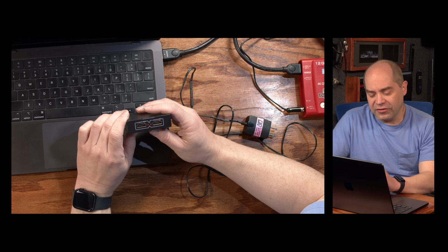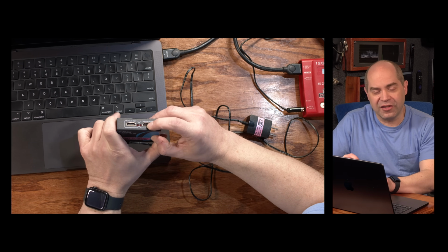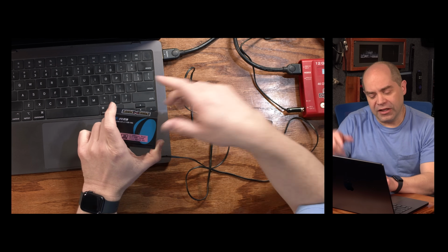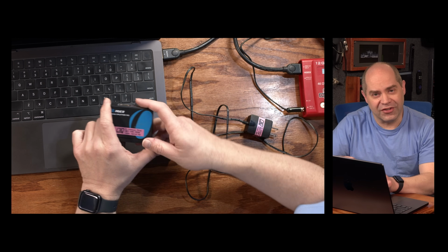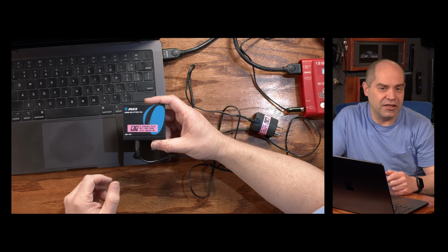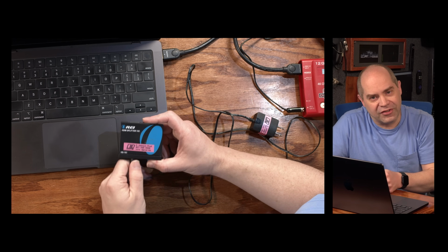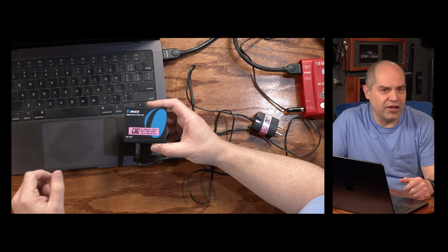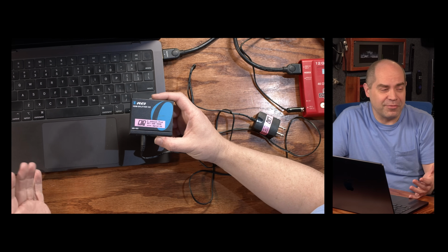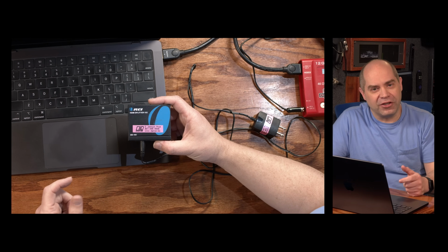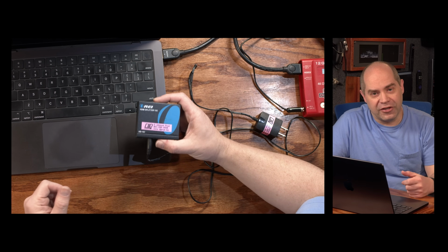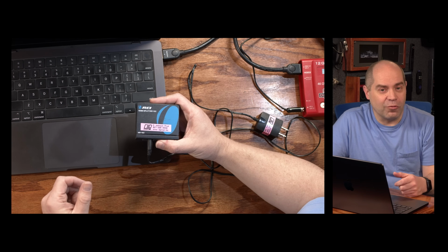So what happens is we take HDMI output 1 and we run that into a monitor or television or whatever, and then we take output 2 and run that into our video production system. And effectively what happens there is the computer is negotiating with the television for that EDID information rather than our video production system. And I find that that actually generates a much higher degree of success, particularly with 4K, just because it's working with a device type that Apple has tested. And basically you're getting the second HDMI output on here for free, and that's the one that you run into your video production system, and you're able to get a working signal that way.